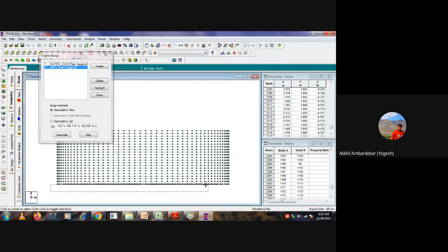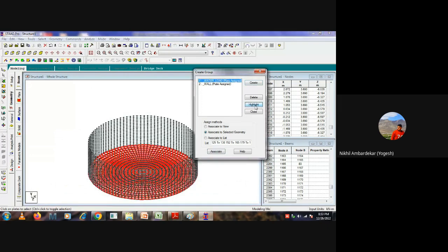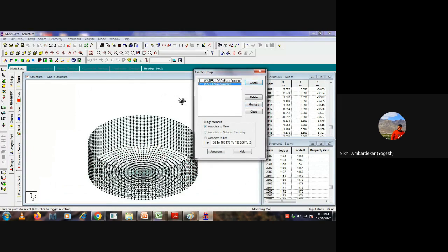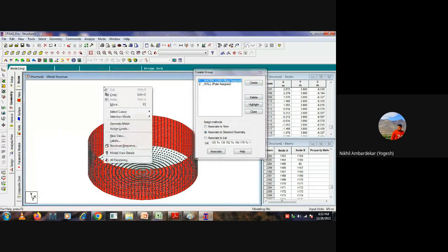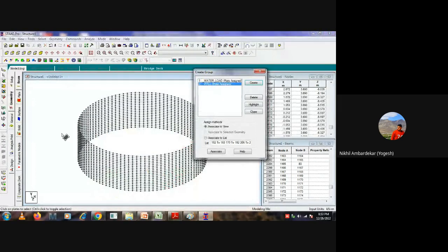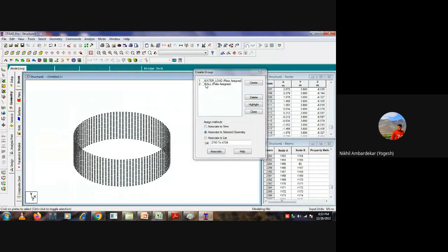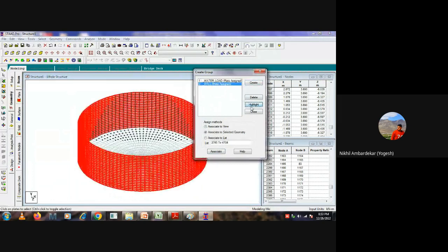When we did that undo, it just got deleted. Is it okay now? Water load. Okay. Now we will assign the wall plate. So highlight, select inverse plate. Now select all the wall plates, associate. Just check again. Base slab, wall plates, done.